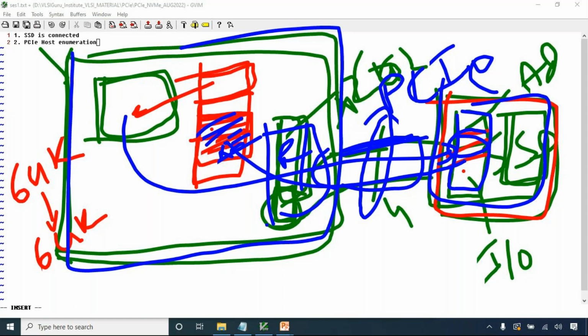Going forward, we'll talk about what is configuration read, I mean, how much data it can read. So it initiates a series of configuration reads. And the medium used for that configuration read and configuration write is the 4 lanes that we have used for connecting these two devices. And those 4 lanes are working on the PCI Express protocol. So once I have performed the read, that whole configuration header information has come to me.